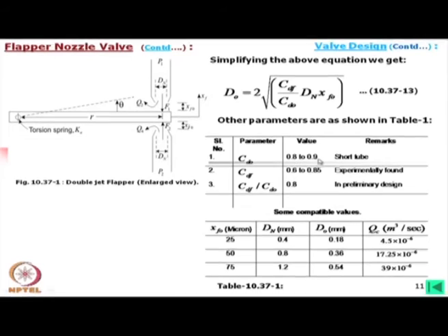That means this is actually a capillary short tube, because in comparison, in case of these orifices, the length is very small, a very thin plate and then a hole, whereas in these cases a certain length is there, but it is found that using such a short tube orifice is better from the control point of view.